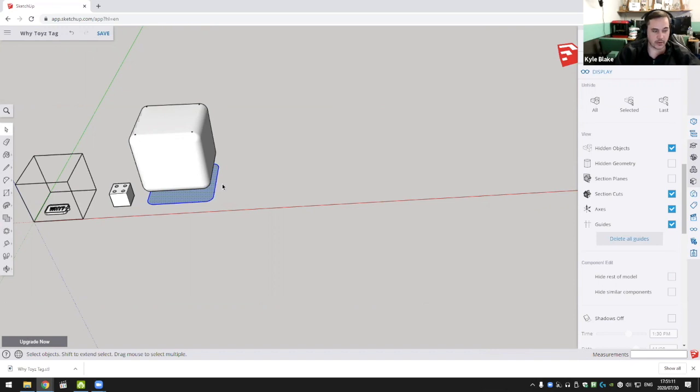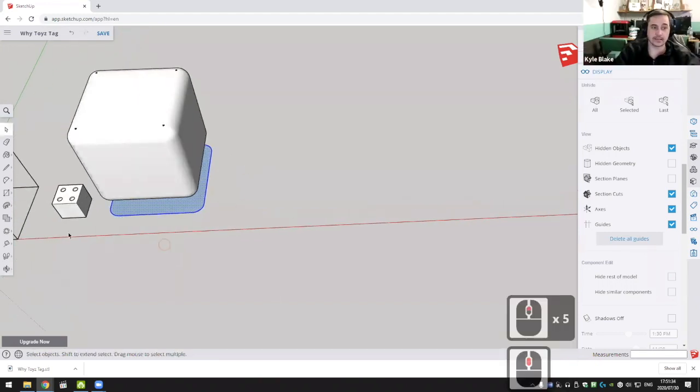He wanted something that had quite a lot of grip in it, but he wanted to put an air hose in it so that it was a weighted skipping rope. So you've almost got to imagine the handle in section, like cut in half, and then you can use the follow me tool to rotate that around itself, and that creates quite a nice rounded handle. Because to actually model something round with quite a lot of complex detail is tricky.